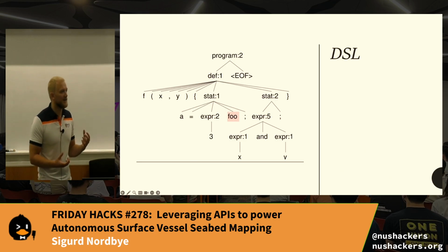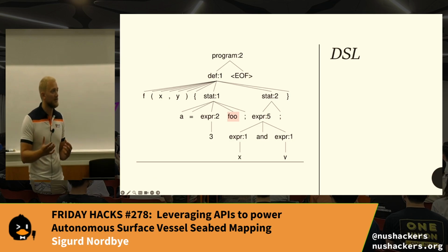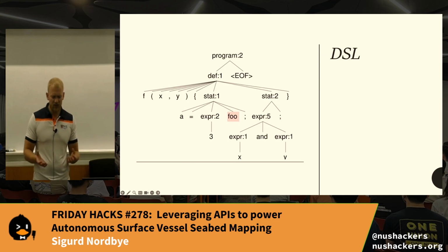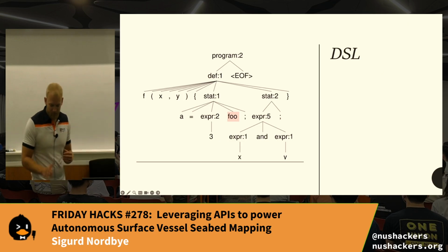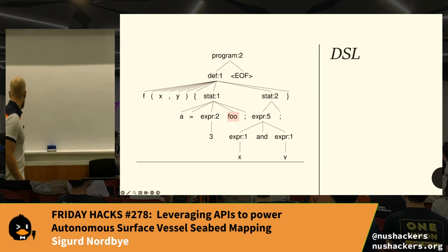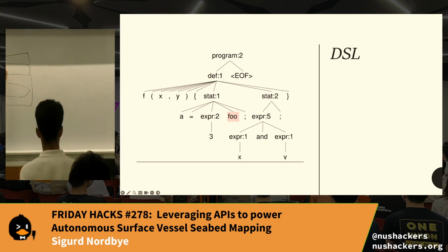And now that I can write a prompt and get a water polygon and then a mission, now I need to actually make a path within that polygon that I have computed, right? So first of all, I just want to showcase generally how path planning works. So I'll show on the whiteboard. A simple approach would be that you have a polygon like this, and you just smack on a lot of lines like this, evenly spaced, and then you connect them, right? So now we have a path in that polygon.